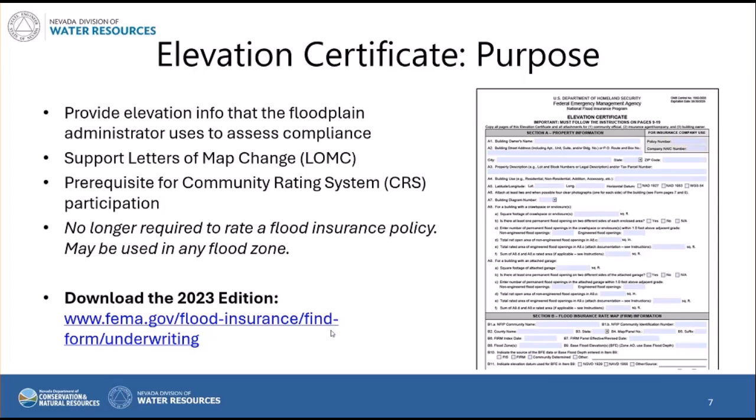While the blank forms expire from time to time, it's important to distinguish that a completed elevation certificate for a structure does not expire unless there's some sort of physical change to the building that would make that EC invalid. Say they add another floor, or an attached garage, or some other internal or external change to the building that would invalidate the old EC. Otherwise, you can continue to use that old EC because it has that certified as-built information.